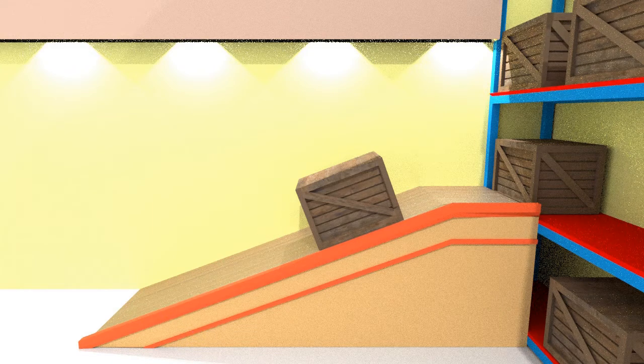Let's first of all draw the free body diagram by considering all the forces acting on the box. The first step in drawing the free body diagram is to see how many supports or other bodies are in direct contact with the box and if there are any external forces applied. As we can see, only the ramp is touching the box. So let's first of all find the reaction developed by the ramp.